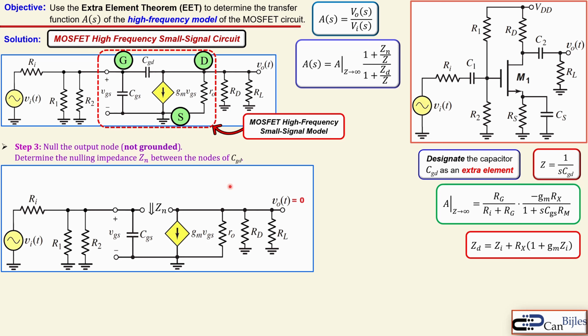And it is actually a similar process where we set a test source, Vd, and associated IT, and that will be then again the ratio where you determine now the Zn using Ohm's law. This is actually a very powerful method, so it will be really handy if you can use this also for other problems, and it will give you nice results. Okay, I will designate this node as D, but it doesn't matter where you designate that.